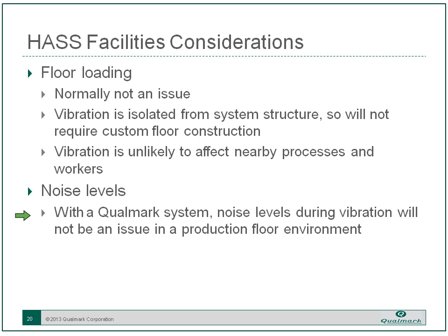If you're running one on a production floor, it won't be any worse than anything else on the production floor, even at maximum Gs. And the nice thing about HASS is you're very rarely running that high of a G level. If you remember the rule of thumb, you're running about half of what the vibration was that you used for maximum in HALT. So the noise levels aren't much of a concern with our systems.